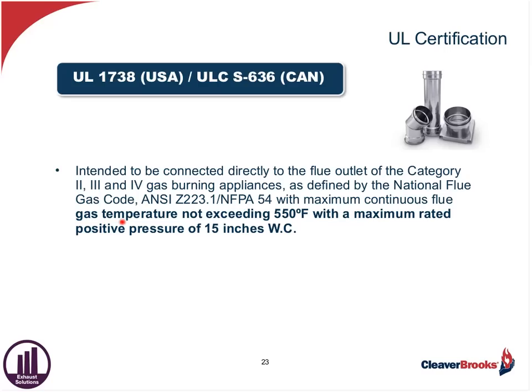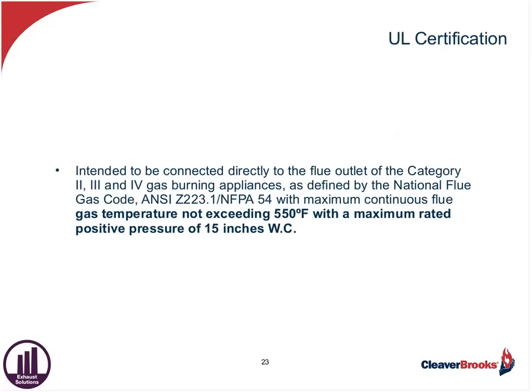And as you can see in the bold type here, gas temperatures not exceeding 550 degrees with a maximum rated positive pressure of 15 inches of water column. That would fall under the category UL 1738 and ULC S636 in Canada.